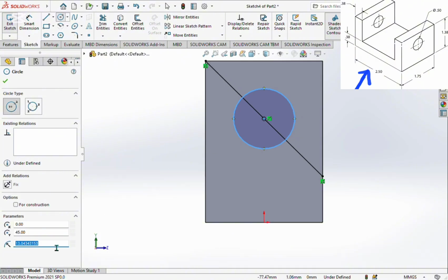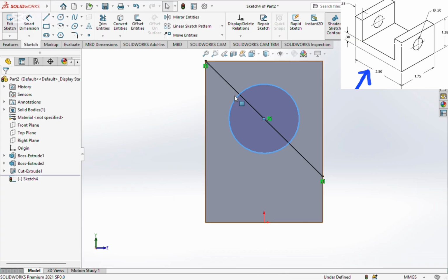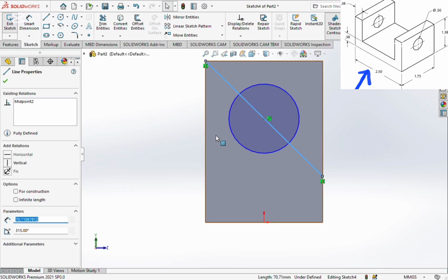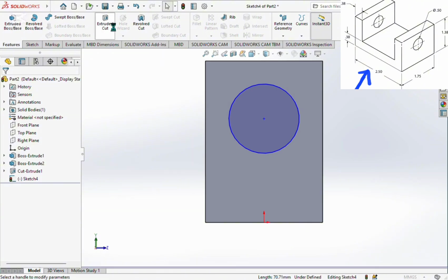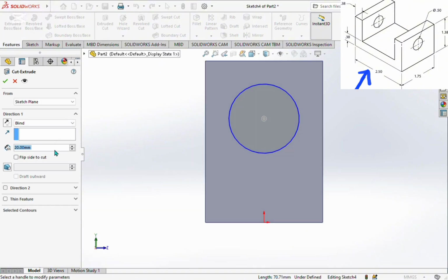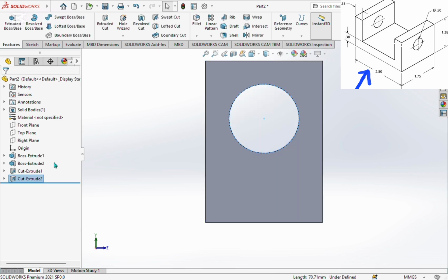We have two circles there. We have the perimeter circle and the normal circle. So I put it at the center point, draw it first, then I edit the radius to be also 15. Now when I make that 15, I enter. Then I remove the line first. I just click on the line and delete it. That's what I did in the former one too. The line has to be removed or else it's not going to extrude.